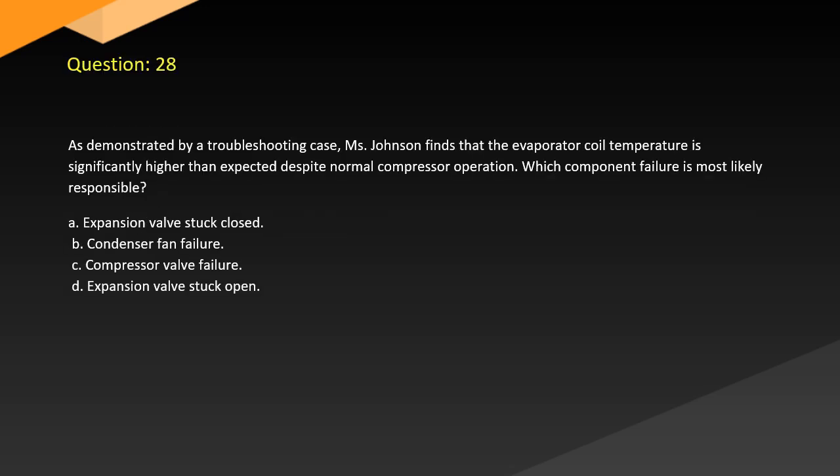Question 28. As demonstrated by a troubleshooting case, Johnson finds that the evaporator coil temperature is significantly higher than expected despite normal compressor operation. Which component failure is most likely responsible? A. Expansion valve stuck closed. B. Condenser fan failure. C. Compressor valve failure. D. Expansion valve stuck open.